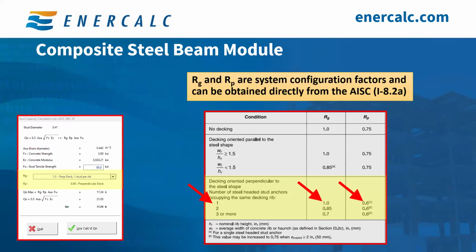You can select the section type from here. So if you're using a W section or an HP or whatever you'd like to use, we're planning on using a W section, and we're going to use a W12 by 22. That's the section that I'm going to start with.